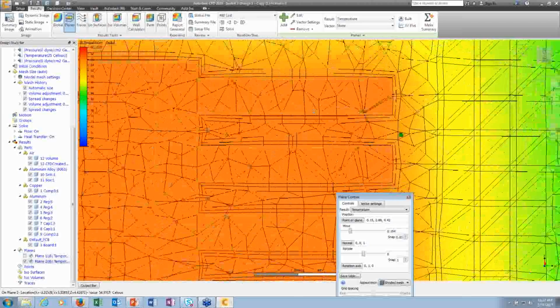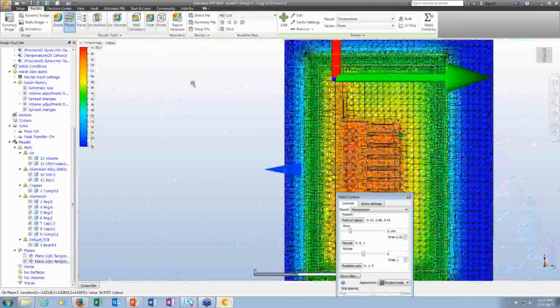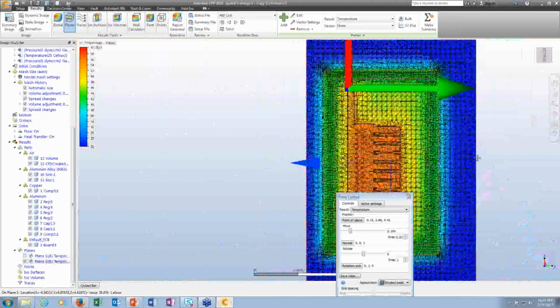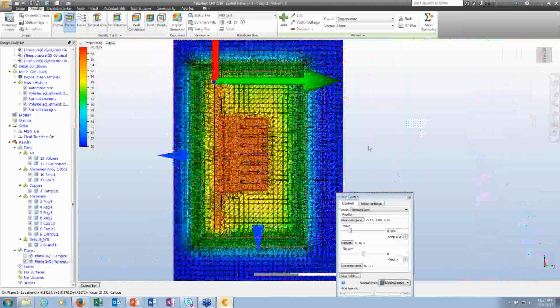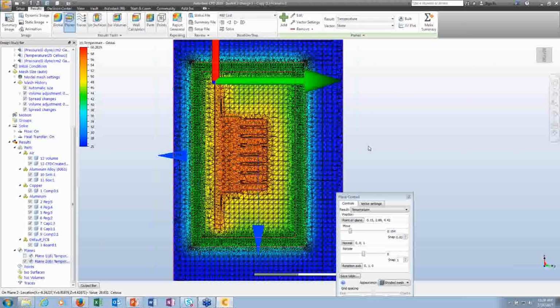Yeah, that's a trick I've been pretty much using more and more. When I was new to the tool, I kind of resisted that, but it's so worth it. So basically between the fin where that air domain is, you would make two separate rectangular volumes, and where those two air volumes are touching, it forces a node there, the way the mesh works, which means you're guaranteed to get two elements, one on each side of the node. And this is of course besides the boundary, the wall layers.